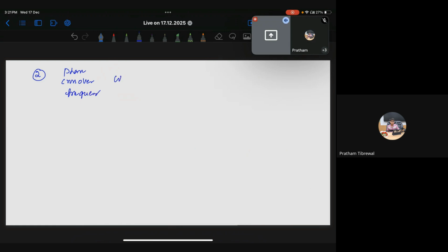Okay, omega PC. How do you find that? The angle you should find has to be equivalent to minus 180. So minus 3 tan inverse omega equals minus 180.